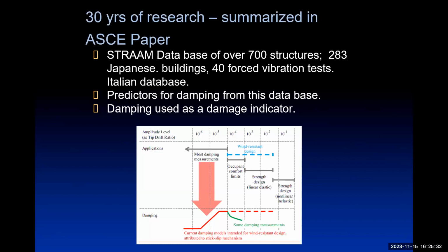And it actually says, yes, okay, we get damping at low amplitude, which has a low amplitude characteristic, and then it rises depending on the material that is used in the structure, and then a high amplitude plateau where there's nothing left to dissipate energy. So what we actually get is this rising characteristic, which is actually dependent on the material used in building the structure.